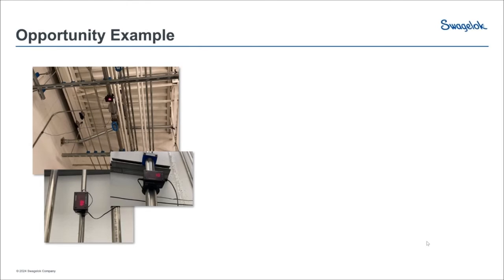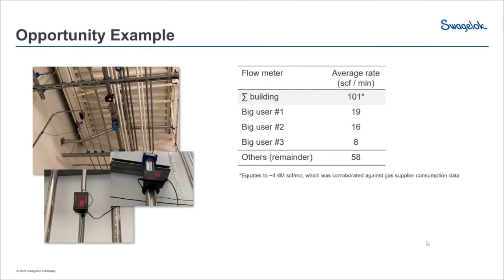So after a few weeks of data collection, we saw a few key trends. First of all, the weekly flow rate consumption, meaning that flow meter at the entry to the building, thankfully was closely matching the data that was given by the gas company. You see, the gas companies, a lot of the times, have built-in telemetry in their systems, and they can monitor real-time the liquid levels in the tank. So it was really important that we knew that our data sets closely matched theirs.